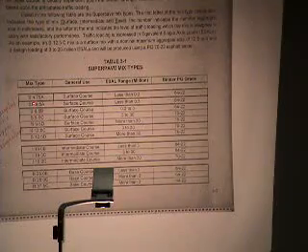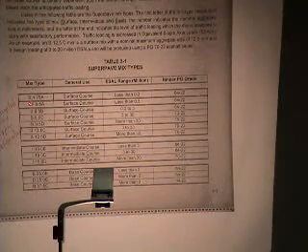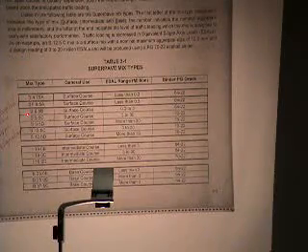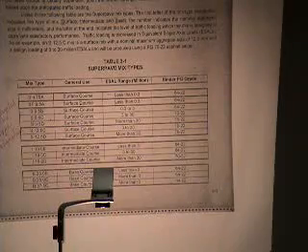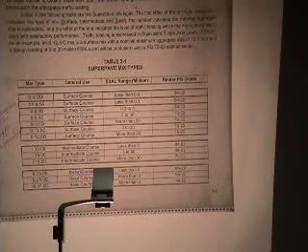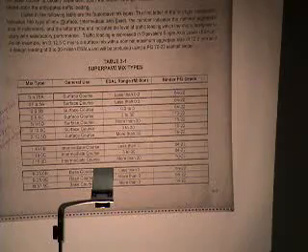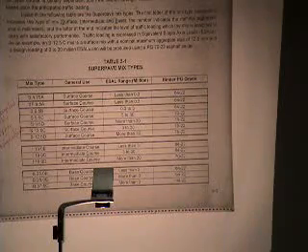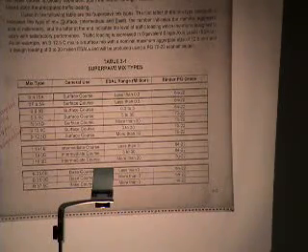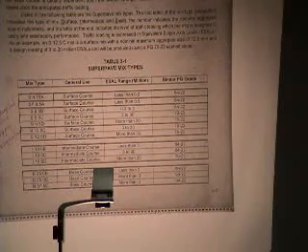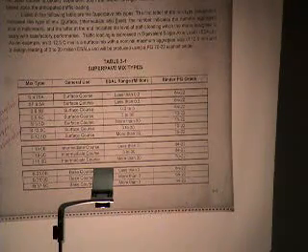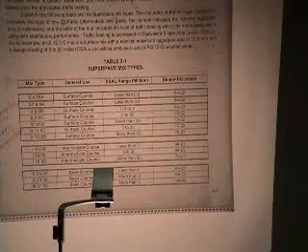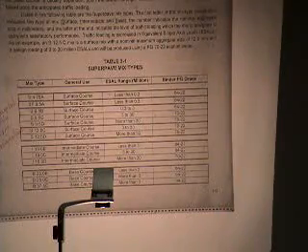One thing I think of, if you notice here this SF 9.5A, whereas the rest of them are just S 9.5s. The SF is a special version of the 9.5 series mix. I always like to think of it as forces the gradation to be on the fine side as compared to what the standard gradation on 9.5 mix would be.